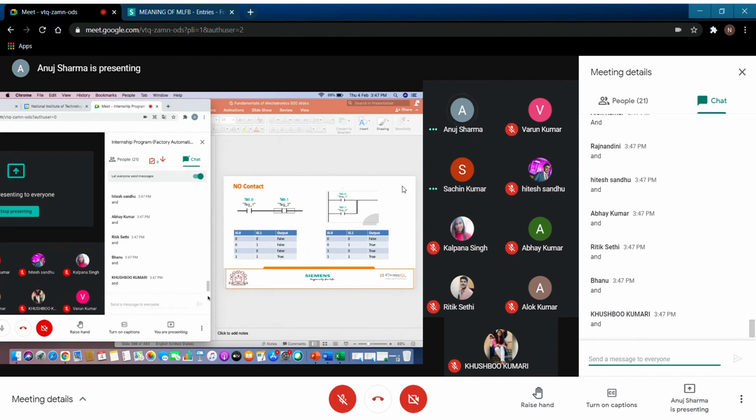Now it can look very easy to you that it is just a 2-step program, but you can understand the weightage, how much ease of process it has brought to your industries. So this single program has reduced all the AND and OR gate operations that are used in pneumatics. A very simple AND and OR gate can directly be converted through a very simple ladder logic.